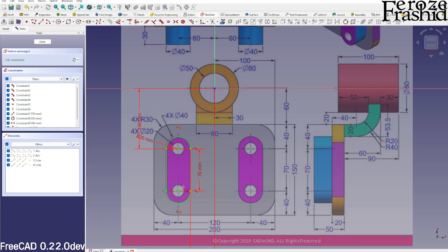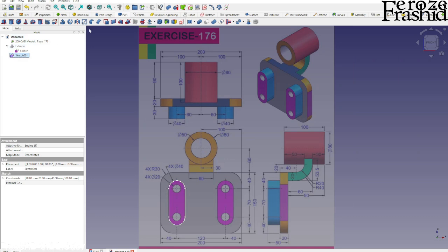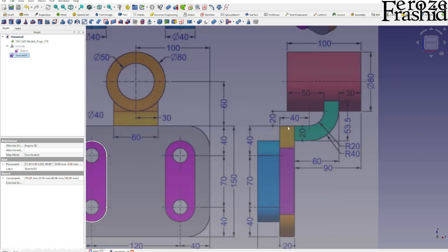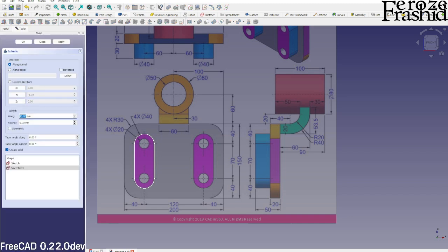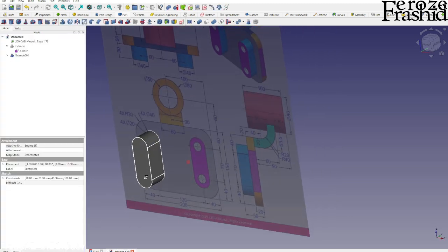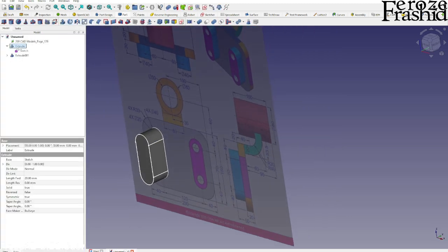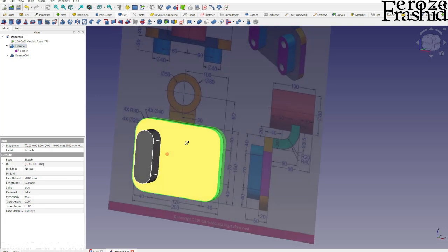Okay, so that part is solid there. And what I want to do is extrude that. So the sketch is right here. That's why we built this sketch, and from there we want to extrude that by 40. So this is given as 50, so we'll extrude that up by 40. All right. So now there they are.